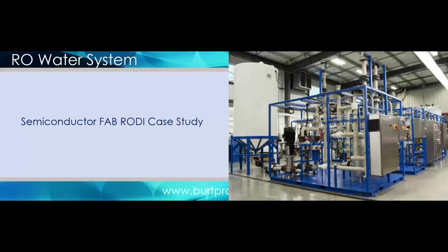Regardless of how clean you make your water and how your loop is designed, over time you are going to get buildup in the actual piping system. So in a lot of ways, it is a function of your water quality, CFUs per mil. Depending on what your CFU per mil count of your water quality is, that depends how often you need to sanitize your system.